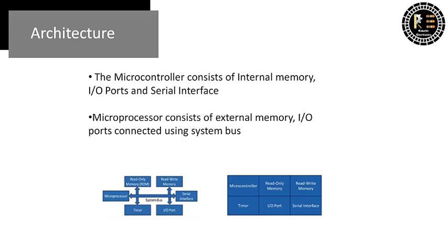Whereas a microcontroller is a standalone device which has internal RAM, ROM, and other peripherals like an analog to digital converter, and I2C and SPI communication links. A microcontroller provides a fixed amount of RAM that cannot be changed. These are the differences between the two in terms of architecture.